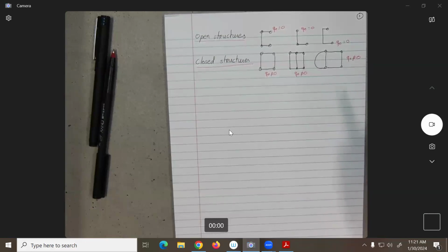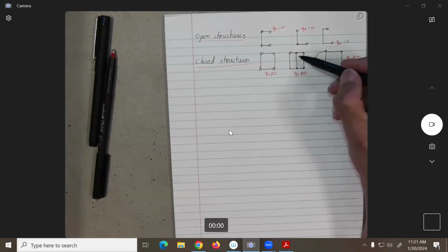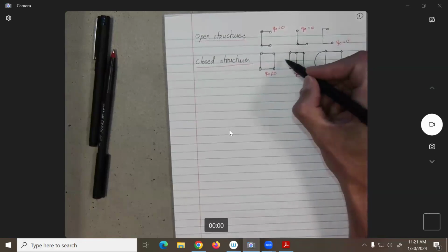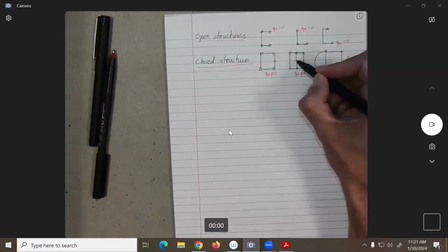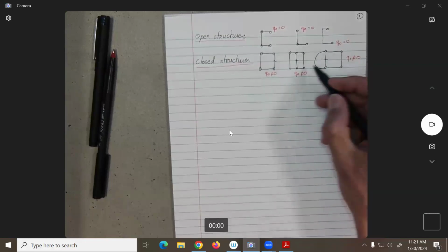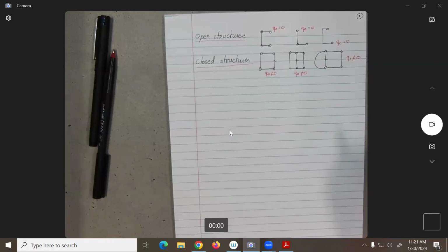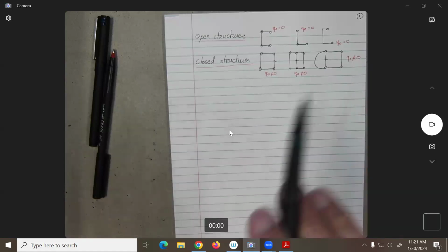What I will do is make a cut somewhere, no? If I make a cut here, or over here, or over here, I will say that is my starting point, so all of my Q will be 0. But at the end, I will have to find an equivalent Q that will substitute for the cut that I made.